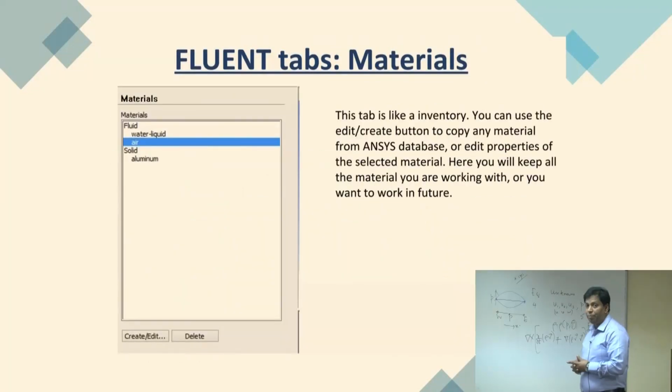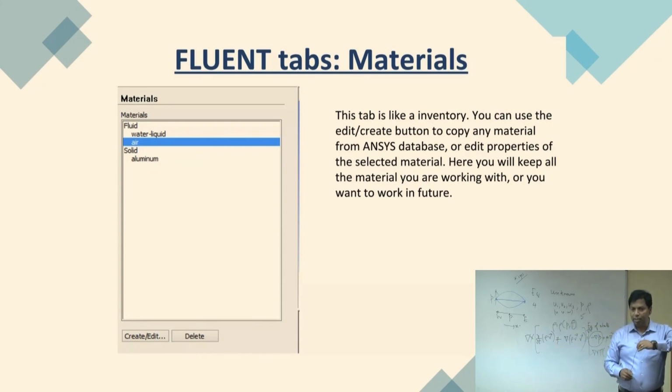Now the material properties. Okay. So which material are you going to use? In the Ansys model, we have a library of materials. Okay, you can choose from there. Or if you know your own properties, you can select something like air and click on it and change the properties according to your data. The name doesn't matter, so you can actually do it.